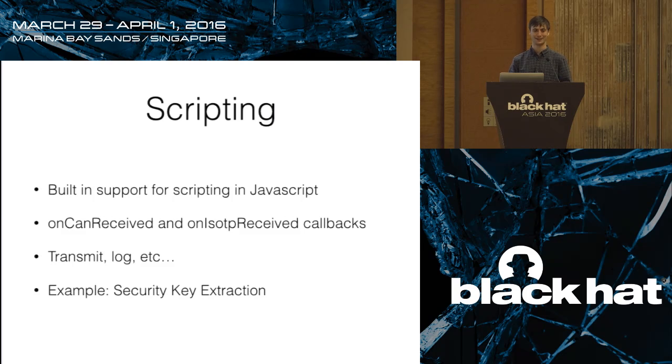I did this for about 10 different values, and then realized that it was just arithmetic. There were 2 bytes. The first byte you added a number, the second byte you subtracted a number, and that was the entire authentication mechanism. So it took 10 or 15 minutes to whip up a little script that pretended to be a car and did this, versus figuring out how to dump the firmware, getting the right tool, opening it up in something like IDA and going through that. This seems to be sometimes a more efficient means of doing it, especially when the tools are trusted.